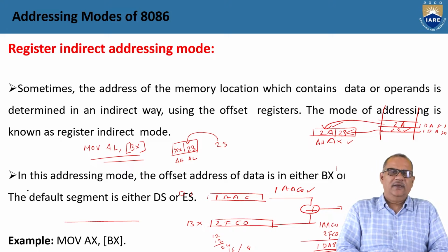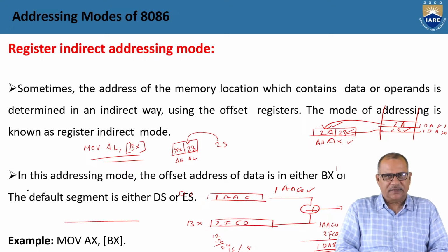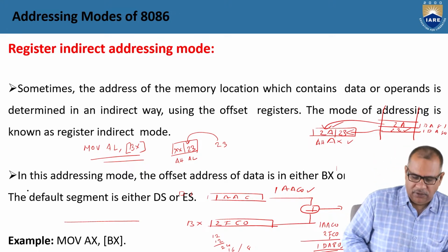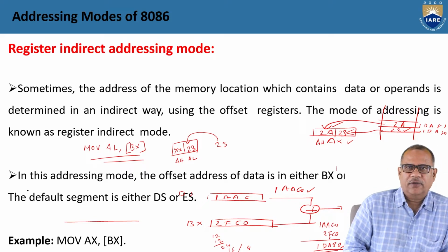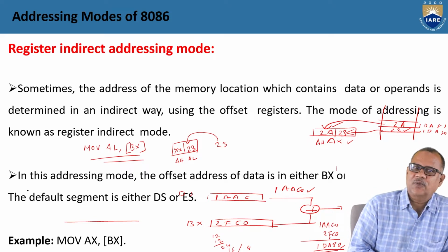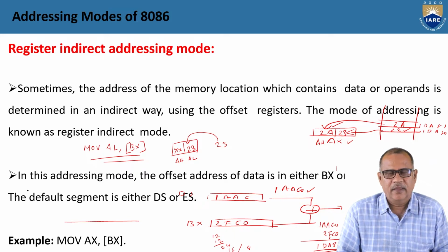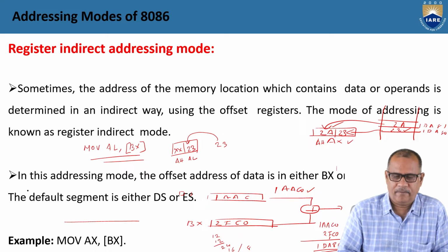You can transfer either 8-bit data or 16-bit data using the 8086 microprocessor. Basically, the 8086 is a 16-bit processor, but to have compatibility with designs made using the 8085 microprocessor, the facility is provided to act upon 8-bit operands also.